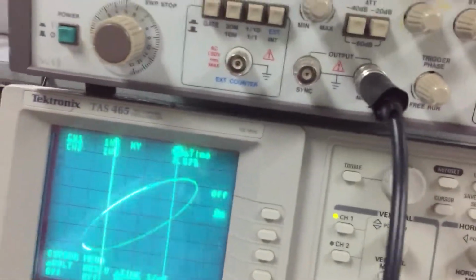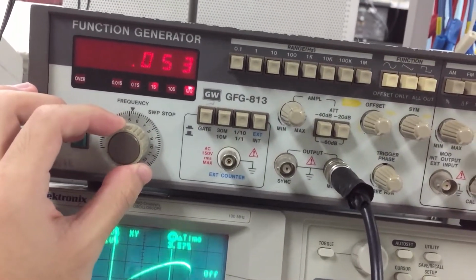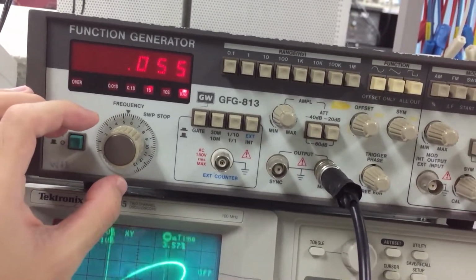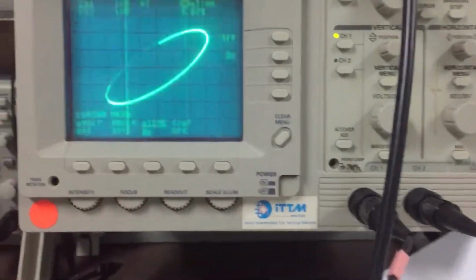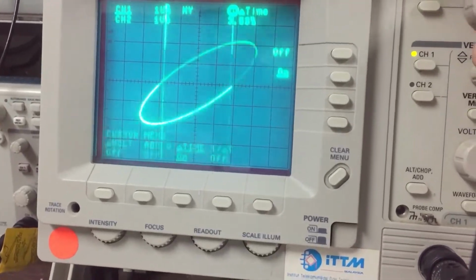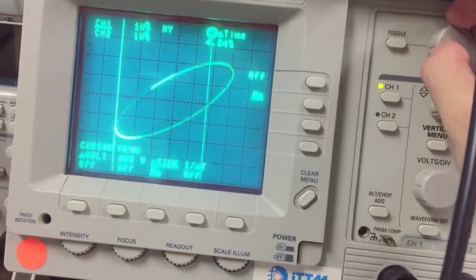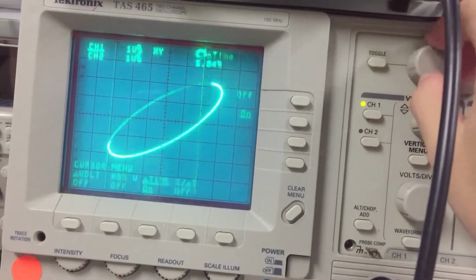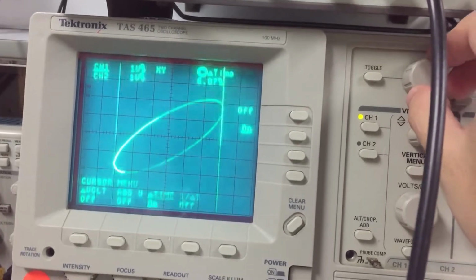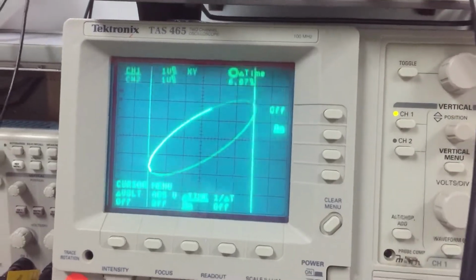Alright, now we need the other measurement for 55 Hertz. What we need to do is just toggle the function generator to 55 Hertz. So we slowly turn this button to 55 Hertz. So repeat again to measure the source peak to peak voltage. We toggle the button to the edge of the Lissajous figure and toggle it to another vertical line and measure the source voltage, which is 6.07, which is close to 6 volts.